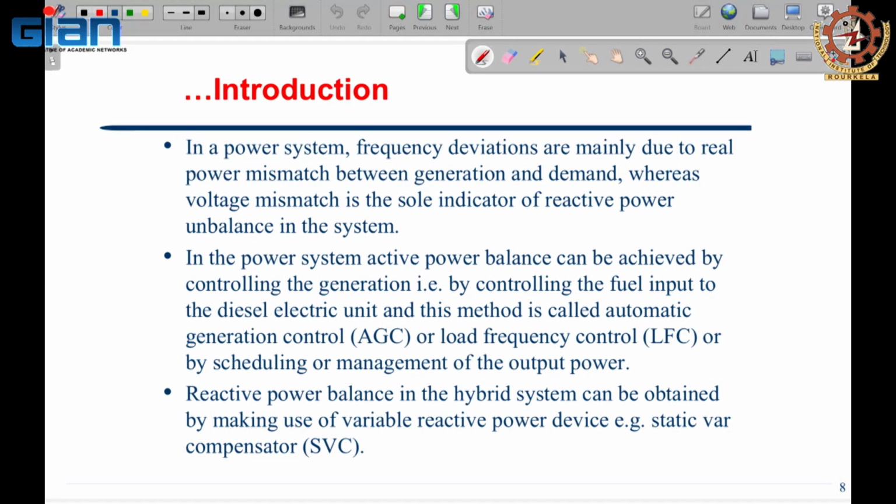So, here we will talk more about that. You have to see in a power system what elements, what devices consume the reactive power, and what devices, what elements produce the reactive power, and then accordingly you provide the balance. For example, as we know, an induction motor will require reactive power. That inductive reactive power you compensate by providing capacitor banks.